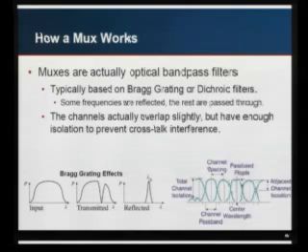And basically here's the terminology broken out. The channel spacing is based on the center of the channel. The channel isolation is between the point of maximum signal to the point where it crosses over into the neighboring sideband. What's called the channel pass band is the width that you can actually pass before you do that. Basically the terminology behind that.